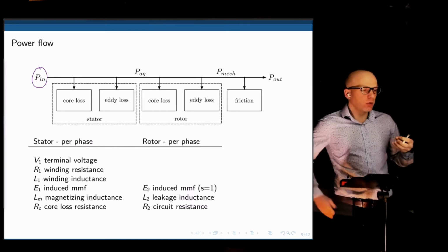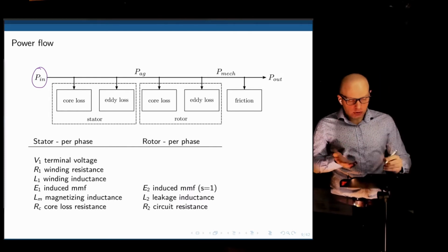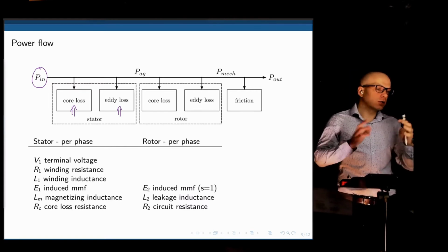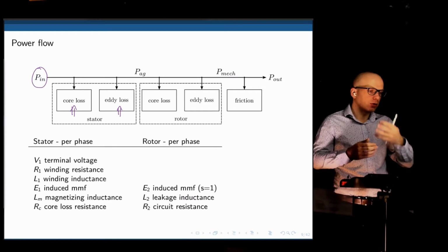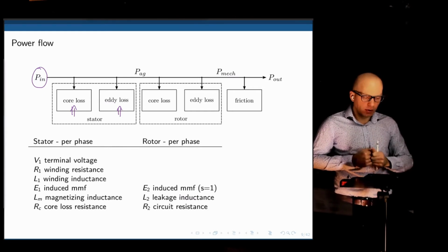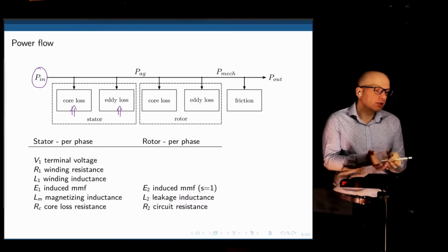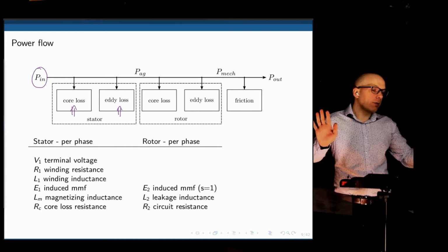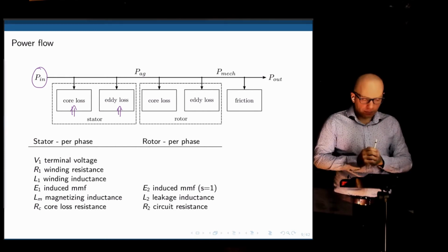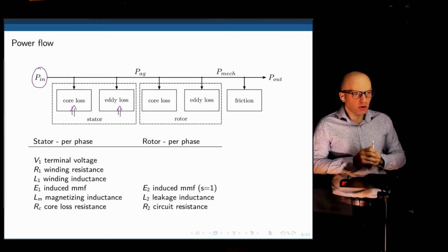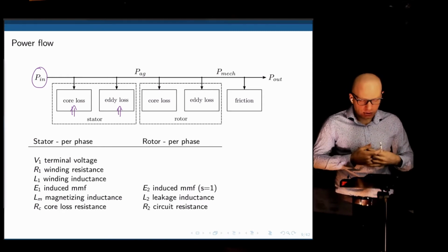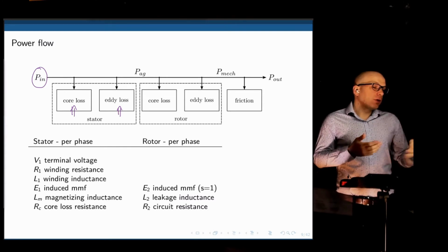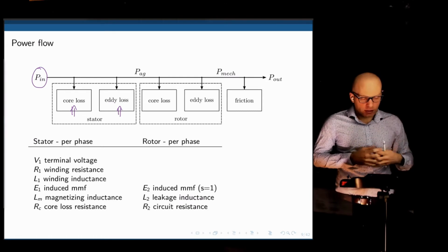If the system operates as a transformer, then you know that you have core losses and eddy current losses. Right? This leakage flux in a transformer represented the flux that doesn't loop in the ferromagnetic path. It is the same here. In fact, it's more significant in the case of an induction machine, because now there is an air gap between one coil, the primary and the secondary, there is a large air gap. So there is a significant loss in the leakage inductance in this example. Eddy current loss, of course, we have a ferromagnetic path somewhere, there is going to be some eddy current losses.